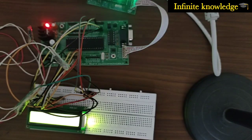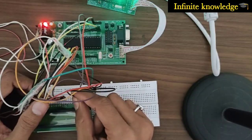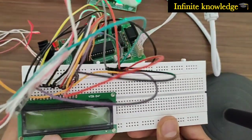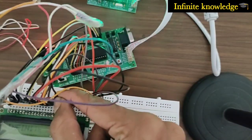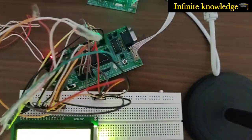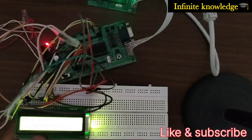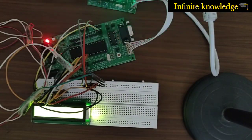Now what is the purpose of this pin? If I remove one of these pins, you can see the light is off, but the text is still displayed continuously. Now again, if I connect this pin, the rightmost two pins are used to supply the back panel green LED. If you don't apply it, the green LED will not glow. If you apply it, it will glow.